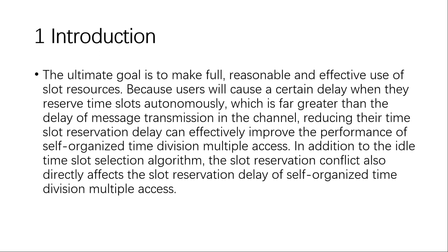Reducing the time slot reservation delay can effectively improve the performance of self-organized time division multiple access. In addition to the idle time slot selection algorithm, the slot reservation conflict can also directly affect the slot reservation delay of self-organized time division multiple access.